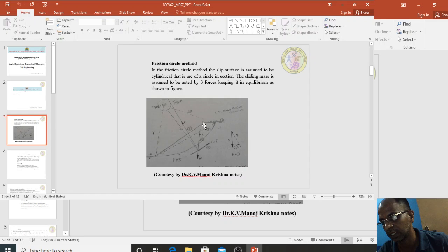Wherever the inclined line and horizontal line intersect, that point will be your B. From B, draw the horizontal line up to D if it is given. If not, with O as the center and OA as the radius, draw a slip circle which cuts the top of the embankment at point D. Thus, the embankment with the slip circle failure envelope has been marked.